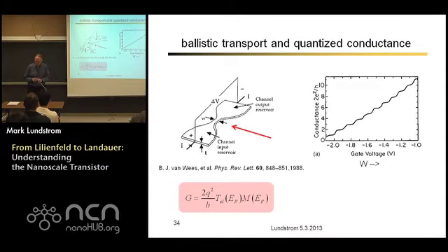People have actually, I understand, taken probes and put them down on a hydrogen molecule, which is about as short as you can get, and measured its resistance. It's 1 over 2q squared over h. Right? So this is some very interesting and fundamental physics that, 25 years ago or so, we thought, well, this is interesting for physicists who are working at 4 degrees Kelvin. Now this is relevant for room temperature MOSFETs.